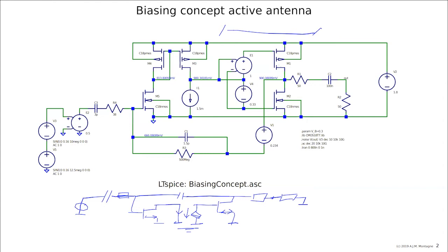I didn't do much about the change of the transistor. I just took the values that we found from the optimum from the previous calculation. And you see here is the 1.8 volt power supply, and here should be a voltage shift of about 0.9 volt, because I want to bias this one in the middle of the power supply just to give me the largest possible voltage swing. Well, this 100 nanofarad capacitor is a battery for a short time, and the voltage across this one will be 900 millivolt. This is called, of course, just simply AC coupling.